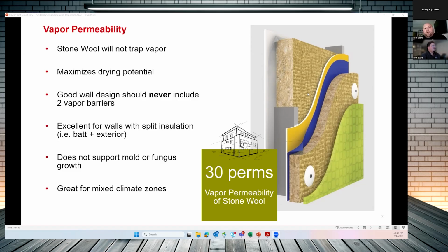When you start to really look at some of these materials you're using for WRBs, it still allows for some drying to the outside. So you have that drying potential to the outside, but it creates a nice air seal. And that's the key. Air moves 15 times more water than vapor diffusion. So if you have a hole here and you allow for air to pass through, well, it's bringing a lot of water into that area. Whereas if we can make this plane nice and tight, now that diffusion, or that vapor just kind of working its way through material, is very, very small.